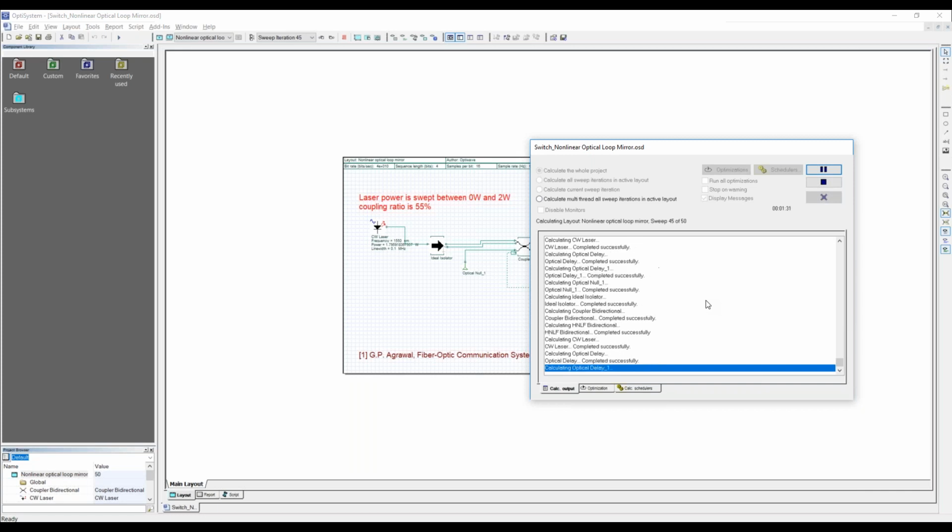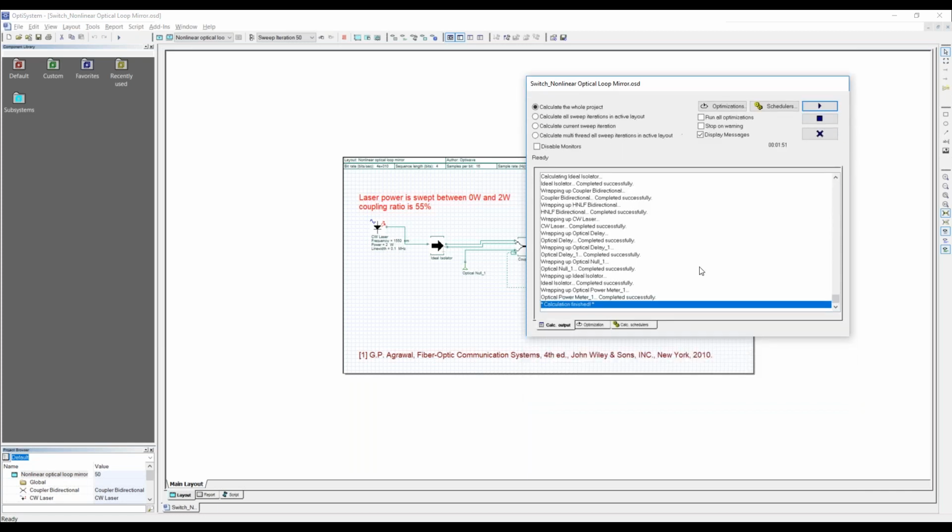Another question is whether it is possible to have the sensor in a full optical link where we have, for example, amplifiers and dispersion compensation and all these things. Again, the advantage of OptiSystem here is that with the sensor application and modeling, you can build your own whole system from all components. Let's say you can add EDFAs, Raman amplification, whatever features you want in the system. You can control the transmission fiber characteristics and all these things, to allow the transmission.